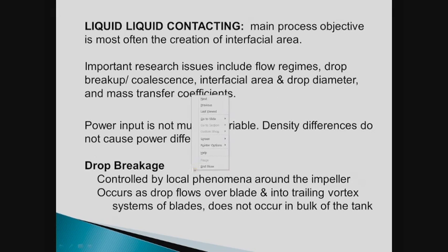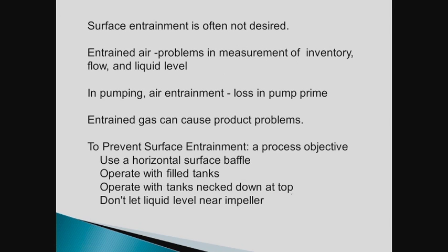We can have a surface baffle. We can operate with filled tanks, right? If there's no surface there, then there will be no air entrainment. So here you could have gas entrainment, but up in here, it's substantially reduced.